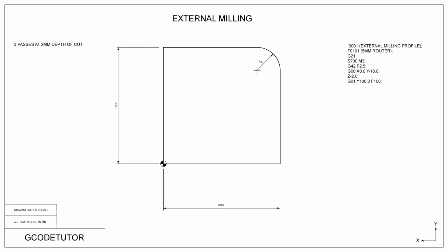Here we have our first G01 move. G01 is our feed rate move, so we can control the speed of the cutter movement. In this particular case, we're moving 100mm up in the Y-axis at a feed rate of 100mm per minute. Again, the feed rate will change depending on many variables. For example, if you're using a carbide cutter on a 5-axis Makino milling machine, we could do this about 6 times faster, but on a home desktop router, slower is better as to not break the cutter.